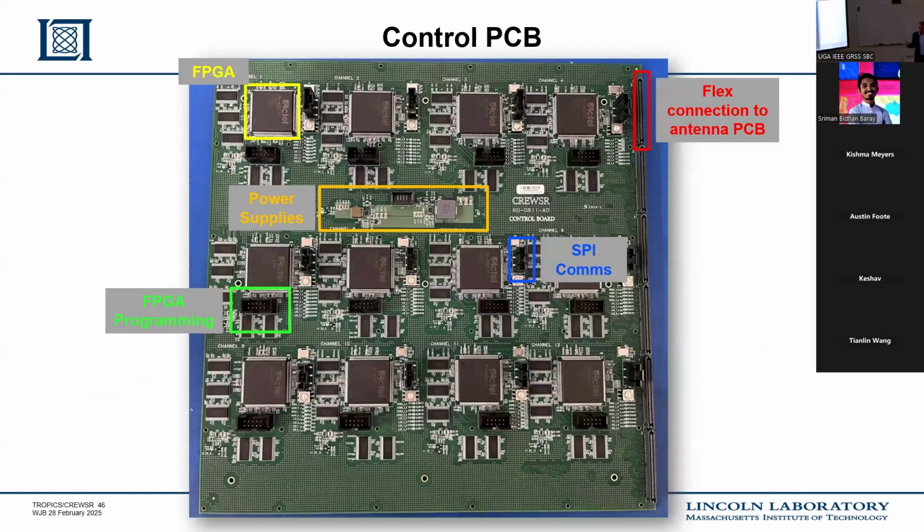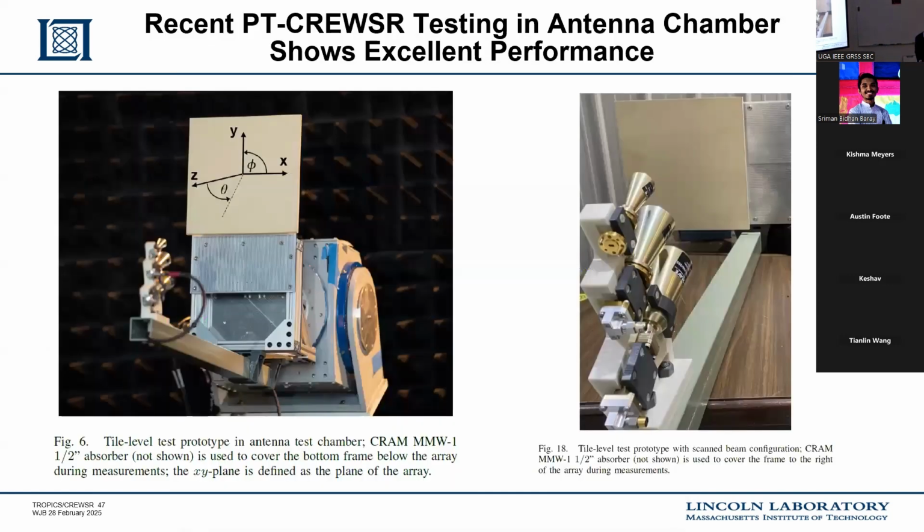There's a challenge of controlling 100,000 chips on the back of this. We've got a network of SPI bus controllers. You guys know SPI? Yeah. So there's essentially a bank. Again, this is on the back side of the board. There's essentially a bank of a lot of FPGAs with SPI buses fanned out to all those chips, right? So we can control that. And this talks back to the main flight computer. So that's how that works.